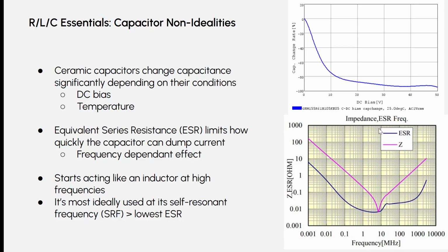With decoupling capacitors on a microcontroller, you have to worry about this quite a bit less because microcontrollers operate around 3.3 volts, and if the capacitance value is a little bit less, it's fine. But when you get into DC-DC power converters, the actual capacitance value is really important for the output stability, and even the controller itself can get confused and make a really unstable output if the capacitance is not what it expects. But I won't dwell on this any further.